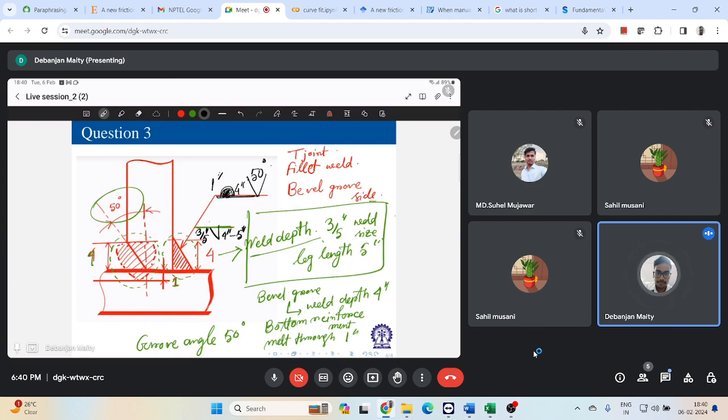Now let's say you have some weld specification provided for a first weld or second weld, whichever it will be mentioned. Let's say this is for second weld specifications. So I am providing CJP as my second weld specification. You need to put the tail over there and mention CJP for that weld symbol. That's how we'll do it for different weld geometry.